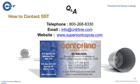Thanks, Mark. One of the important things in designing a solution in any coating application is proper surface preparation. Our coatings training teaches us that about 90% of our resources in formulating a coating solution actually starts with surface preparation. Now, we know that by blasting with various types of media at various angles and pressures, we can affect the morphology of the substrate before the coating is applied, and that's one way to optimize adhesion.